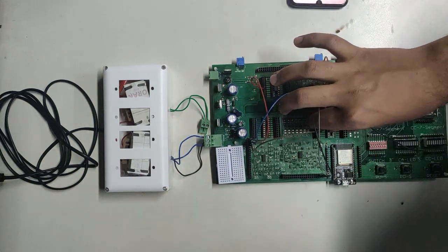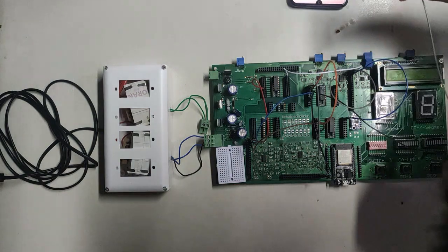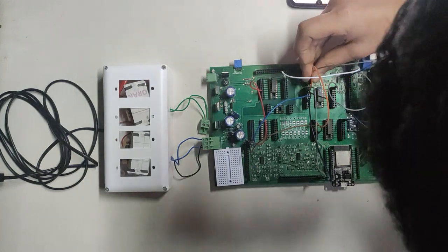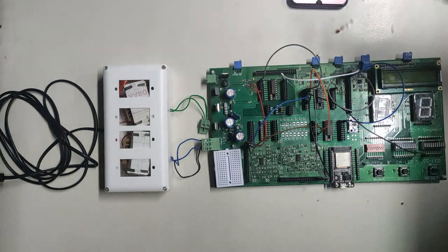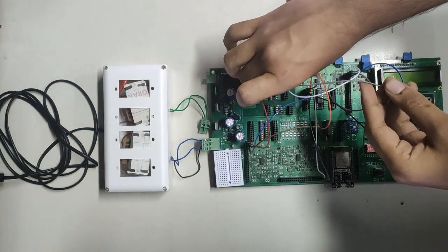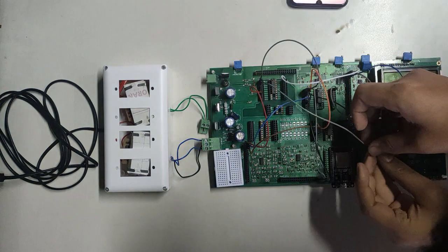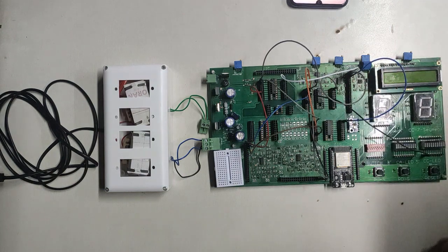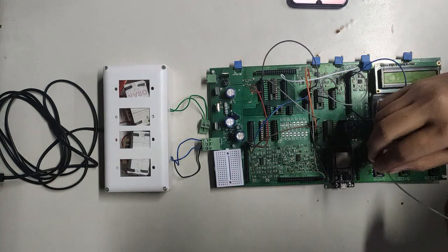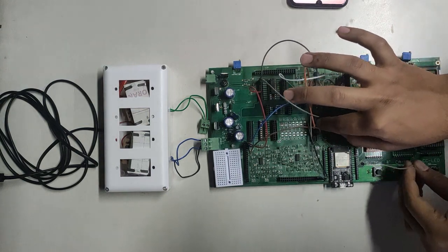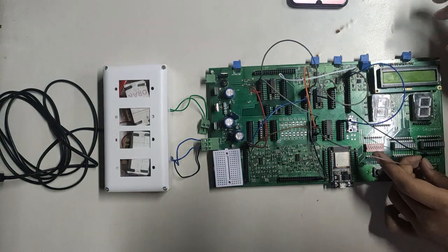This is the first input, and the second input which we are giving to the AND gate must be bubbled, or basically it must first be given to the NOT gate, and then to the AND gate. And the product of these two is nothing but our borrow. So that was our connection.